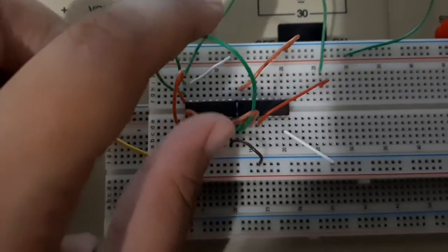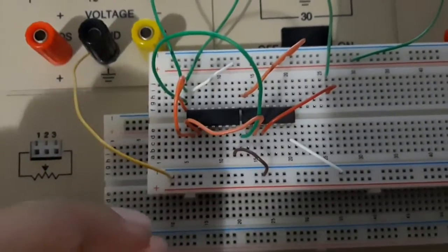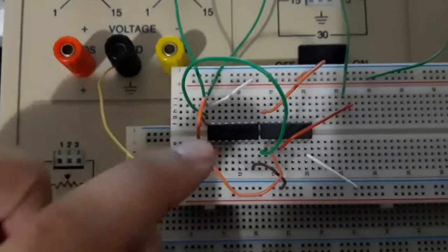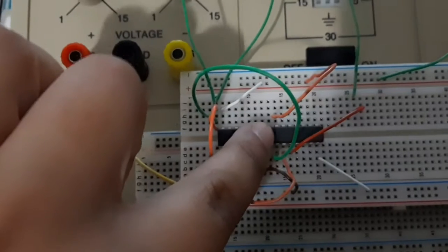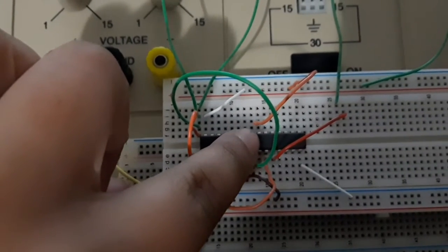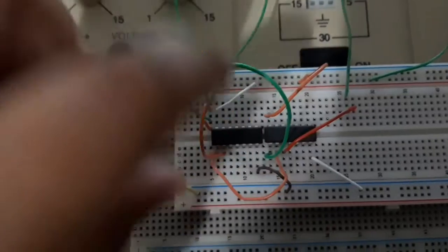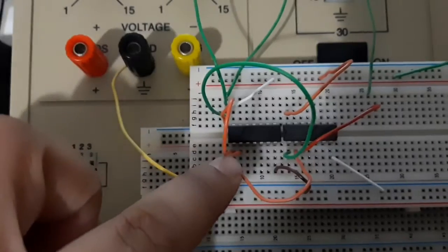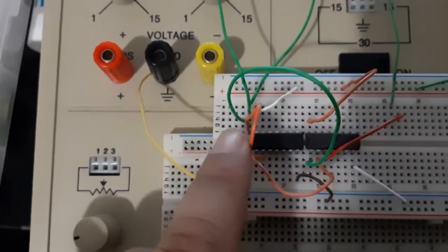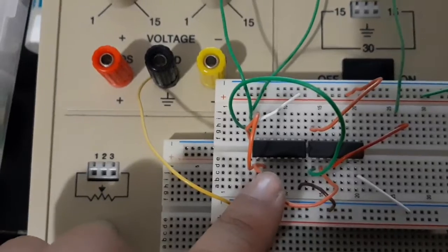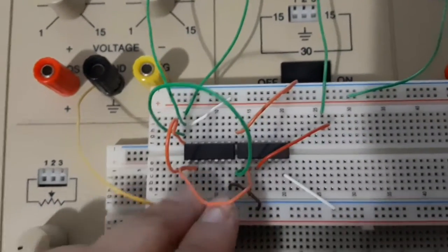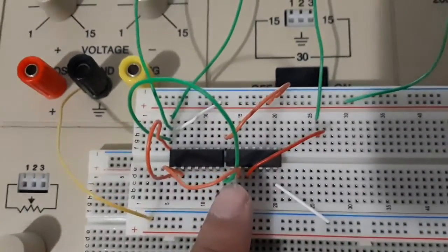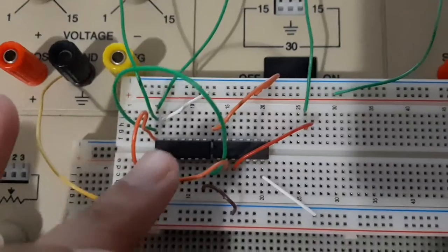Let me pull this one down. 1 Hz square signal going into my 7432 chip, which is the OR gate, to pin 1, which is input A. Then I have another wire going from the square wave signal into the 74LS04 chip to the input, which is pin 1. And the output, which is pin 2, is connected to pin 2 of my OR gate because it is input B. So input B of the OR gate is the square wave signal passed through this inverter.